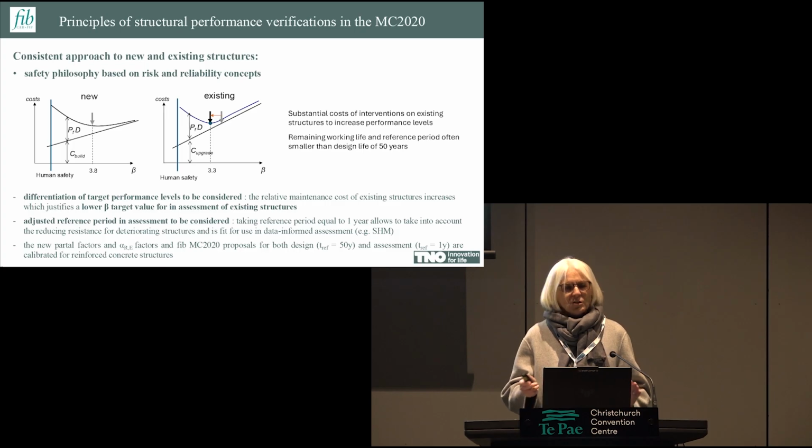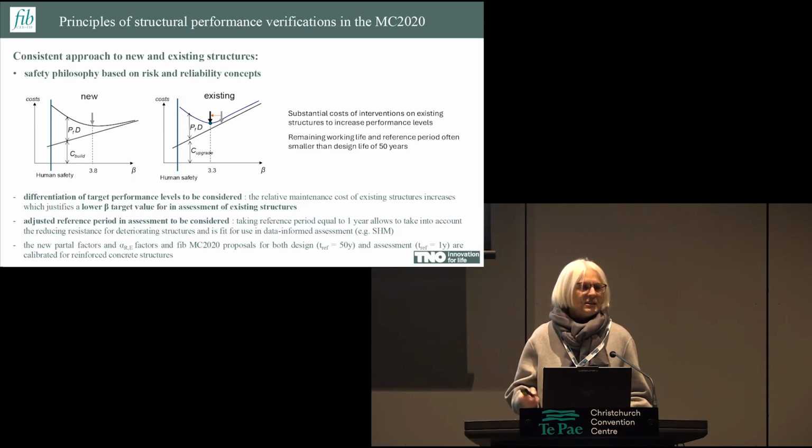No explanation to the slide, but only a message. Structures, new and existing, it's a continuum. Therefore, we look at fib at the safety philosophy's basis from the same principle, risk-based approach. We accept certain risks for certain reasons. How we handle that in our verifications, partial factors, global factors, and other approaches as a consequence of this consideration that have been made upfront. Risks are something that we have to handle, and the observation that has been made is that the costs of minimizing these risks for existing structures are higher than for new structures.